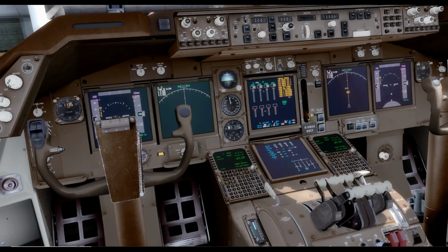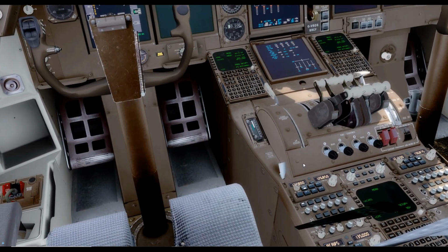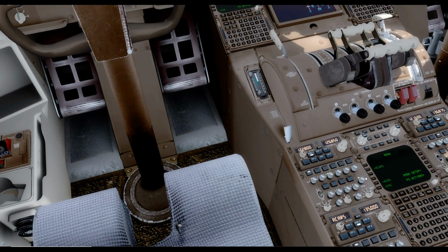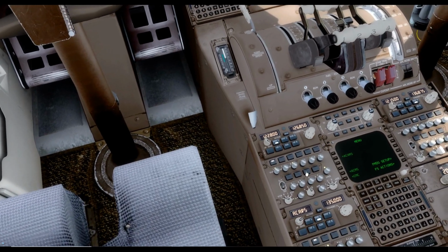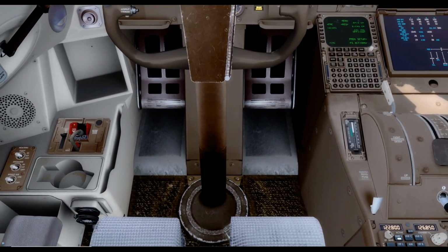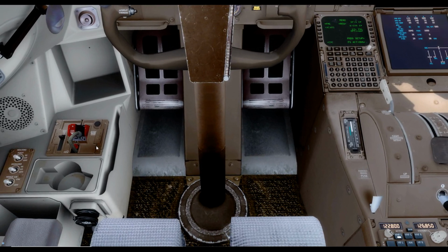We're then also going to select the overhead speaker and the flight interphone option on the audio control panel, and you'll see why in a moment. And we'll go over to the oxygen selector itself, selecting the reset test switch first of all, and making sure there's a yellow momentary cross in the display.